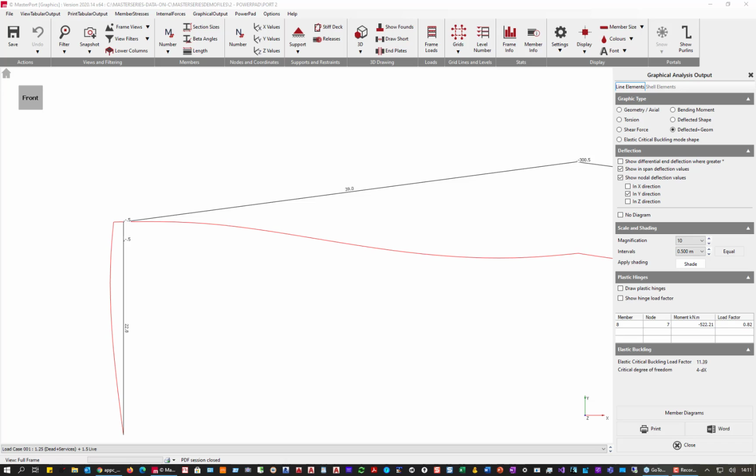Does it have British standard? Absolutely, you can go for British standard on all of our software. How many degrees of freedom in each node? Well, for our general beam elements, you're talking about 6 degrees of freedom, 3 directional and 3 rotational. When you're talking about the FE analysis, we're talking about 8-noded quadrilateral shell elements, so the more accurate quadrilateral elements are used in your analysis.